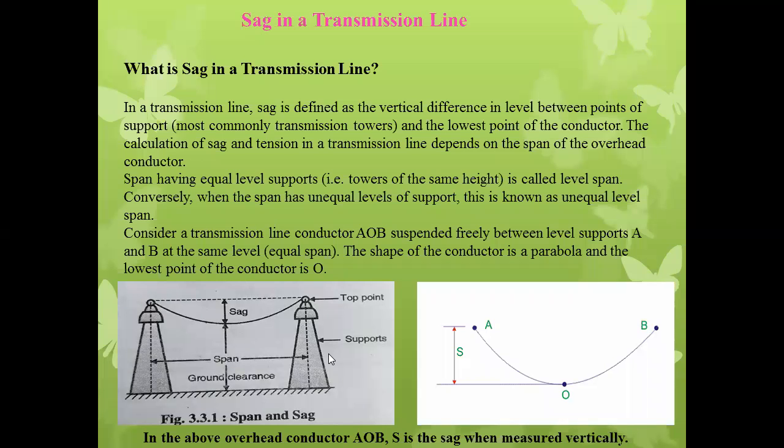That's why sag, tell me, how will it be? Increases. Correct. Whenever the temperature increases, tensile strength decreases and sag will increase. Okay, remember this point.